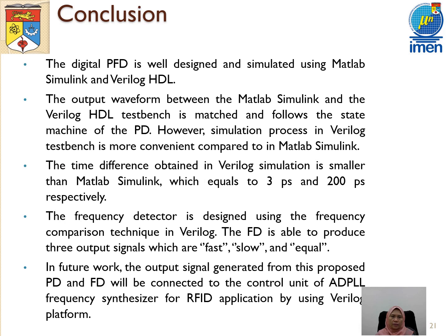And as a conclusion, the digital PFD is designed and simulated using MATLAB simulator and Verilog, because we already tested the design of the PFD using MATLAB and Verilog, where MATLAB gives a very long time difference because we need to insert the delay element in the design to compensate for the dead zone.